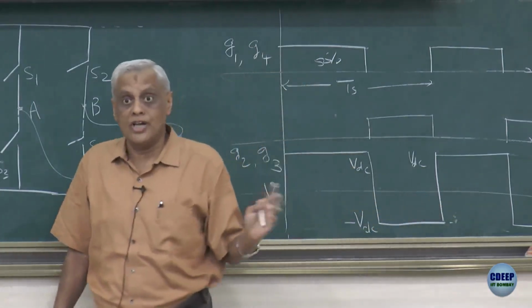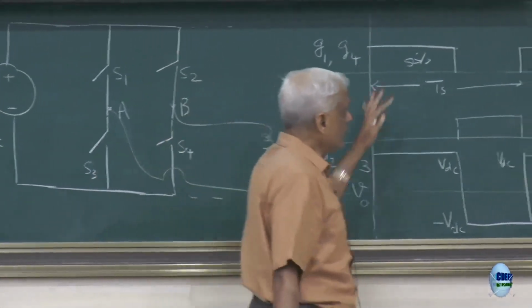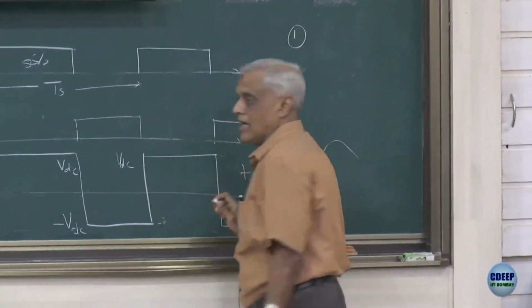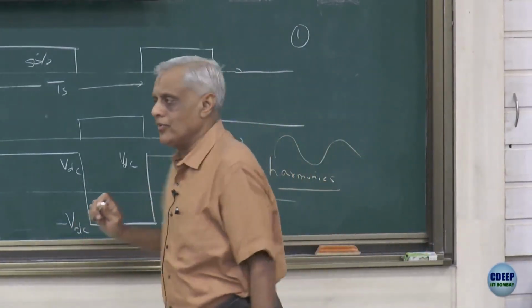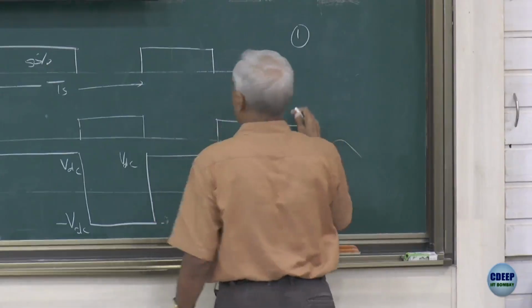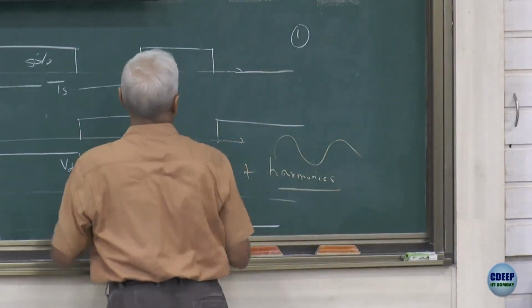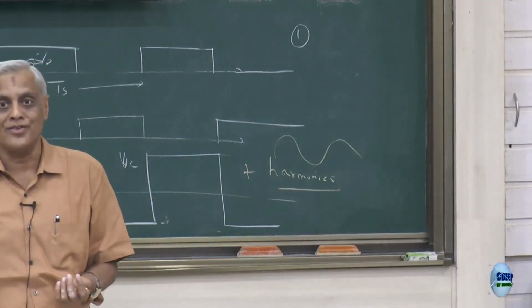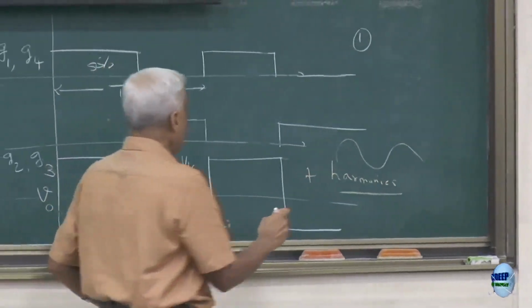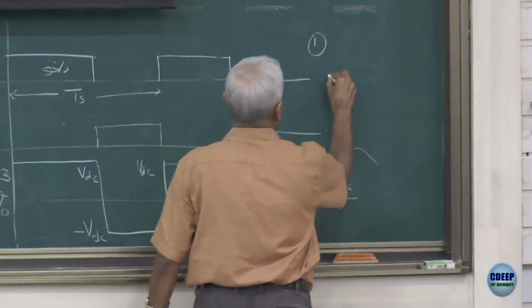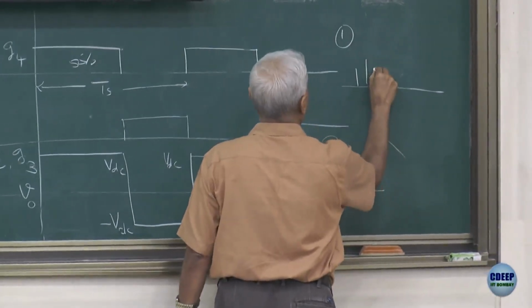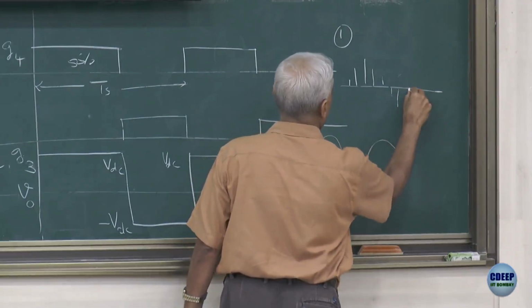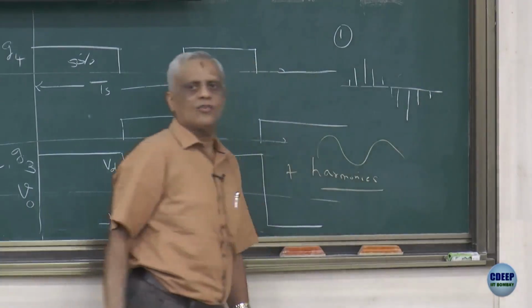And remember, I want to tell you one more thing here, that all these systems, whatever you see here, people have tried, with the advent of electronics and advanced controllers, things like modulation of these pulse widths and later on sinusoidal modulation of these pulse widths, so that you actually end up getting these kinds of components at the output.